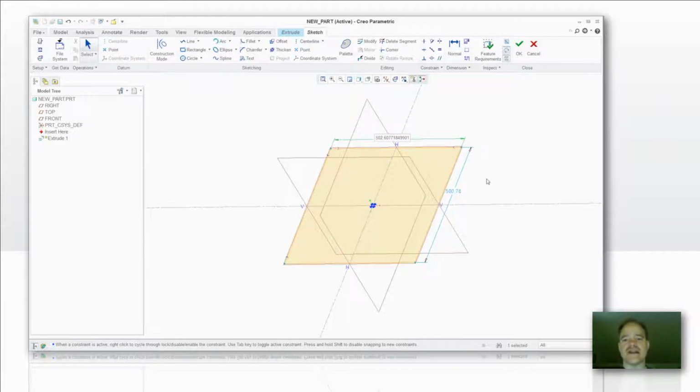Of course, I can go in and highlight all the dimensions that I'd like to make a change to, and then pick the checkbox so that it scales all my dimensions at one time when I change the value of that dimension. But let's take a look at how I can set up a start part as a template so that I don't have that situation.